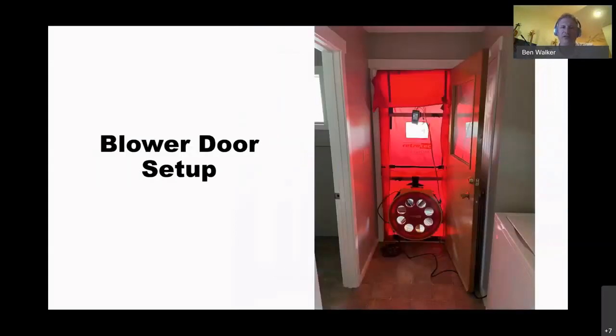So in case you're not familiar with what a blower door looks like, it's a cloth panel that's installed in the doorway to create an airtight seal. There's the digital pressure gauge connected to the top part of the frame, which is connected with hoses to the fan that's used to either depressurize or pressurize the house to, typically 50 pascals. And then the amount of flow that's going through the fan then is what's being pulled in through leaks throughout the house. And then the mobile application is connected to the digital pressure gauge via Wi-Fi.